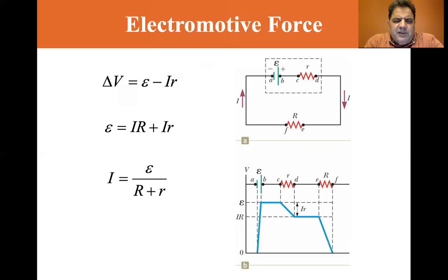Some of you may have seen a small drop. Your power supply may have said 10 volts, but you were only reading 9.9 volts when you were reading the current through the resistor. That may have happened. And so I times E, that's the power. It's equal to I squared times the big R plus I squared times the little r, the internal resistance.